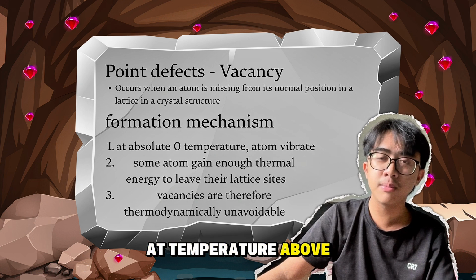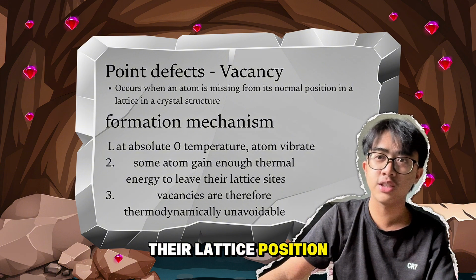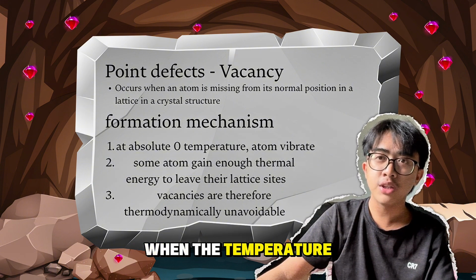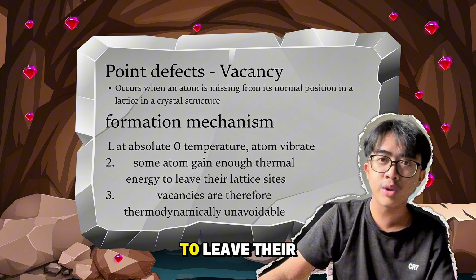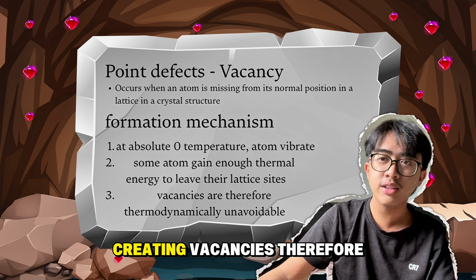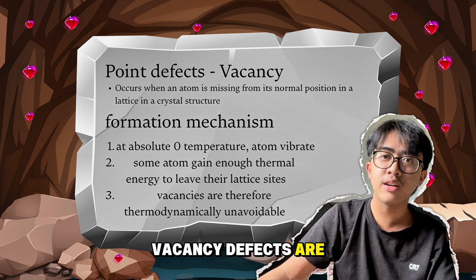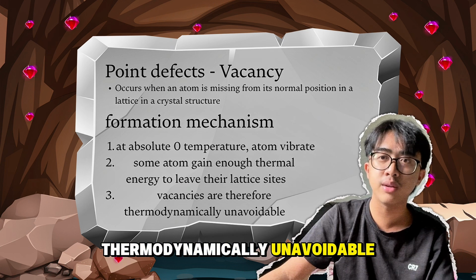At temperatures above absolute zero, atoms vibrate around their lattice positions. When the temperature increases, some atoms gain enough thermal energy to leave their lattice sites, creating vacancies. Therefore, vacancy defects are thermodynamically unavoidable.